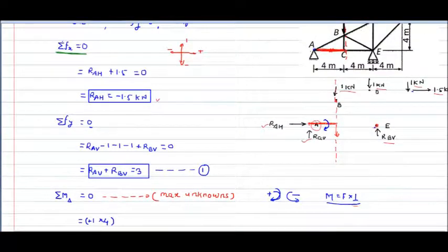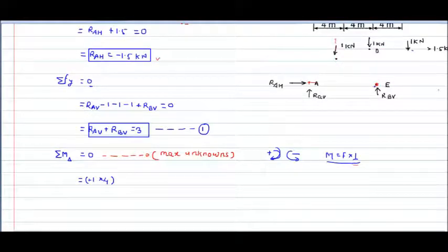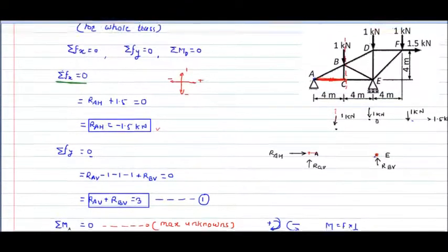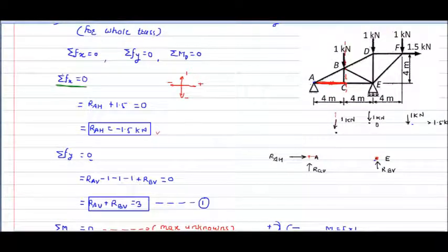Now in a similar way we can calculate the moment because of this second force, that is the 1 kilonewton force. Once again I will draw the line of action for this 1 kilonewton force here. Actually my figure is a bit not to scale, so this way my line of action is this, and I'm doing this just to get the perpendicular distance, because students generally get confused with the perpendicular distance. So I need to use this method again and again, but once you get habitual to this, you need not apply this step.